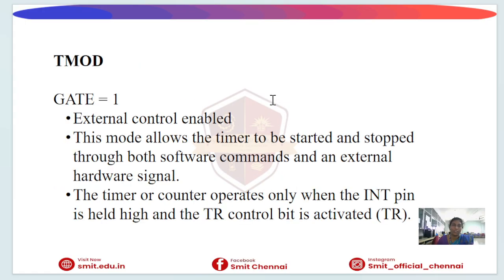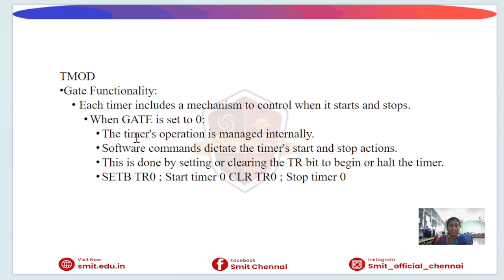Then in TMOD, the GATE bit determines whether the timer is controlled only by software or also by external hardware. If the gate is 1, the timer runs only when the INT pin is high and the TR bit is set. Whenever the gate is 0, the timer runs solely under software control. In most applications, gate is set to 0.